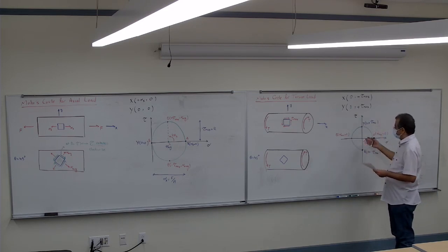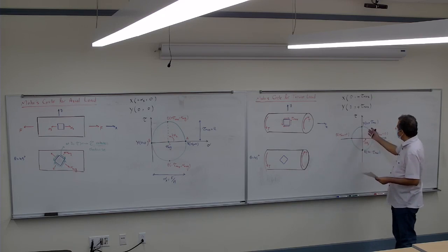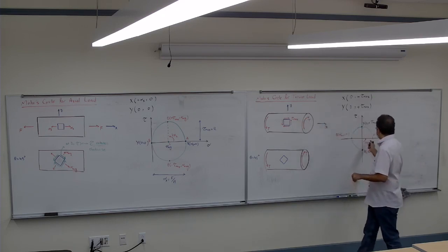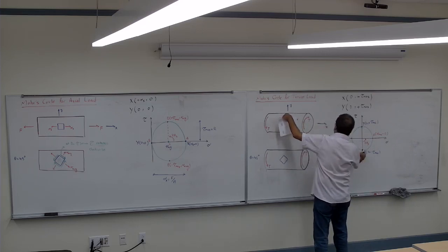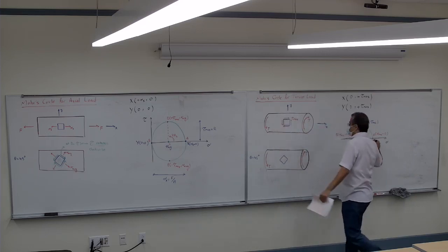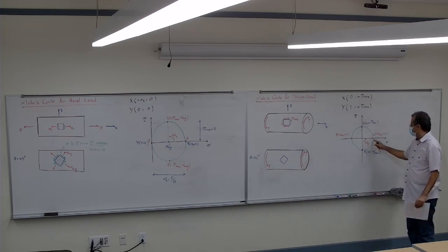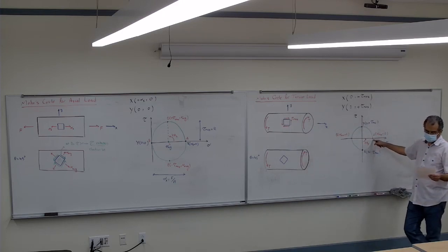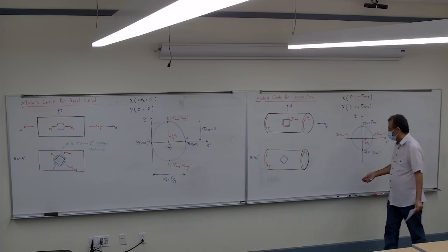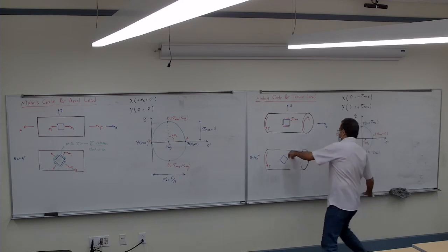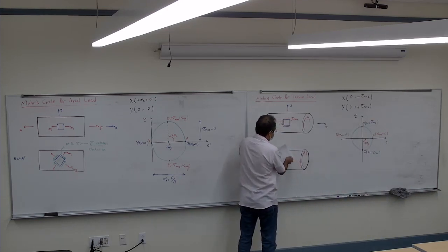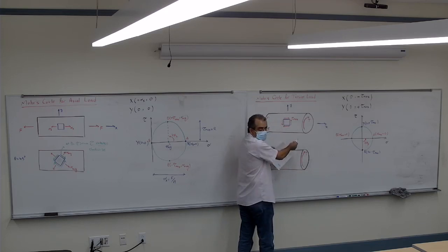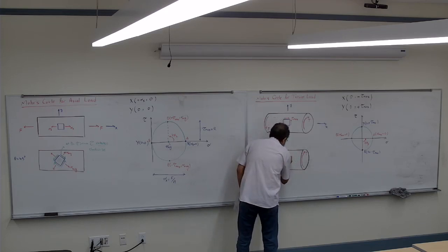Now, if I rotate 45 degrees from where I am, so I'm here and I rotate, that's my X, correct? The X is there. And I rotate 45 degrees, I get to the point A. What happened at the point A? Sigma is now max. So this is my face, now it is there. It was 0, now it's there, so it's going to be sigma max.